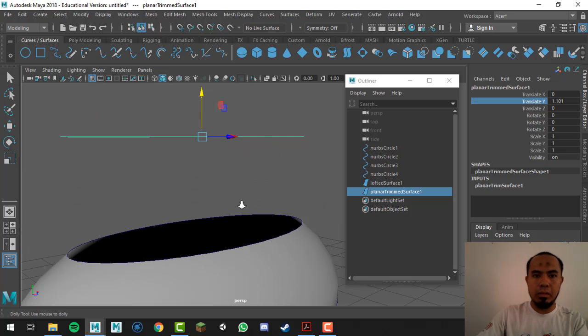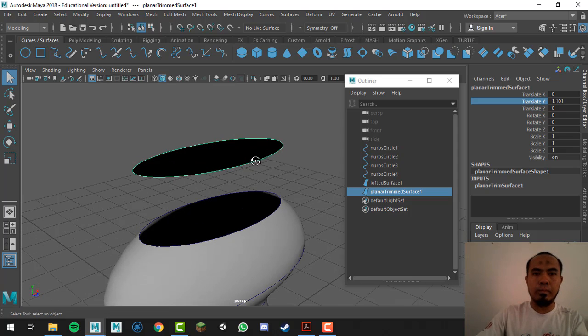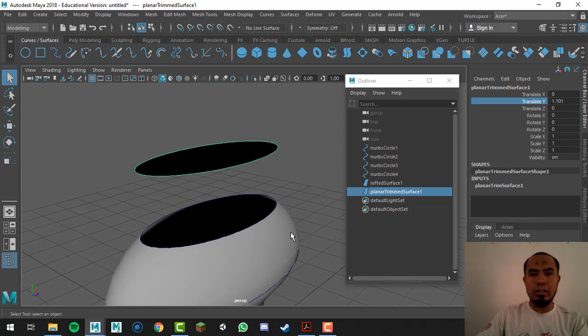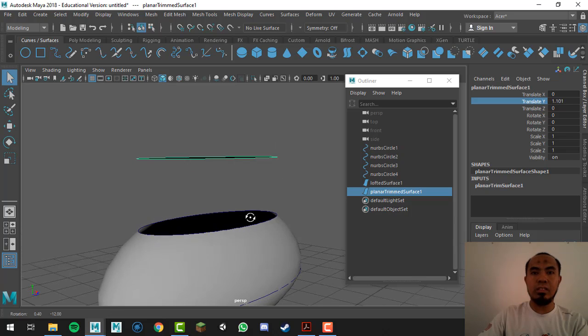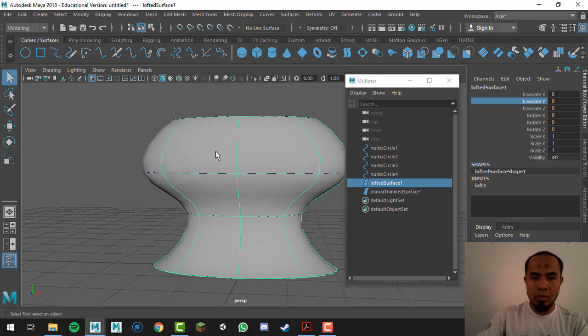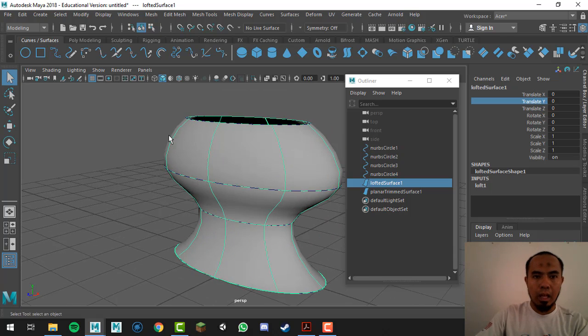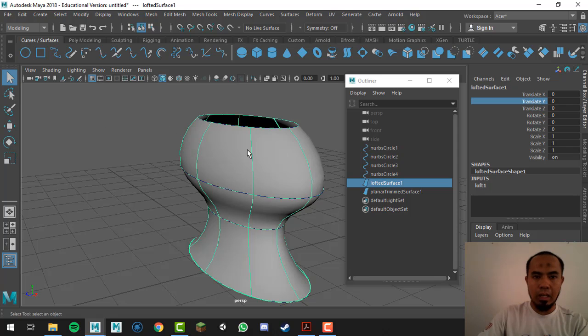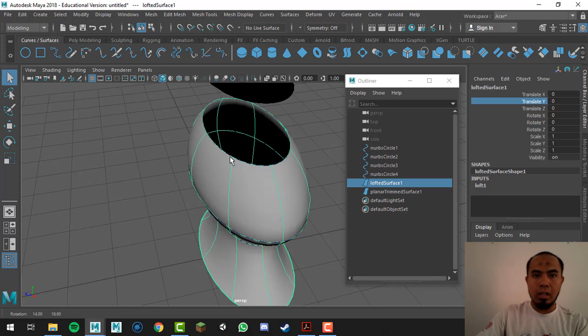So I'm going to bring it up here, and I want to show you something. We have this thing in 3D that there is always one right way whereby the face is looking. It means that every single face, every single surface in 3D will have a right way which it is facing, and this is called the normal. For instance, this surface here, the one below, is all pointing out towards the scene, and that's why you're seeing it to be gray.